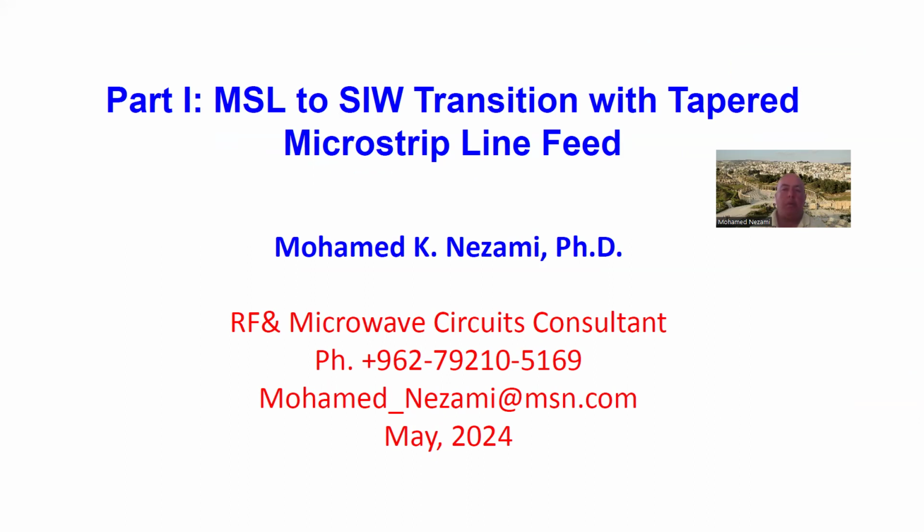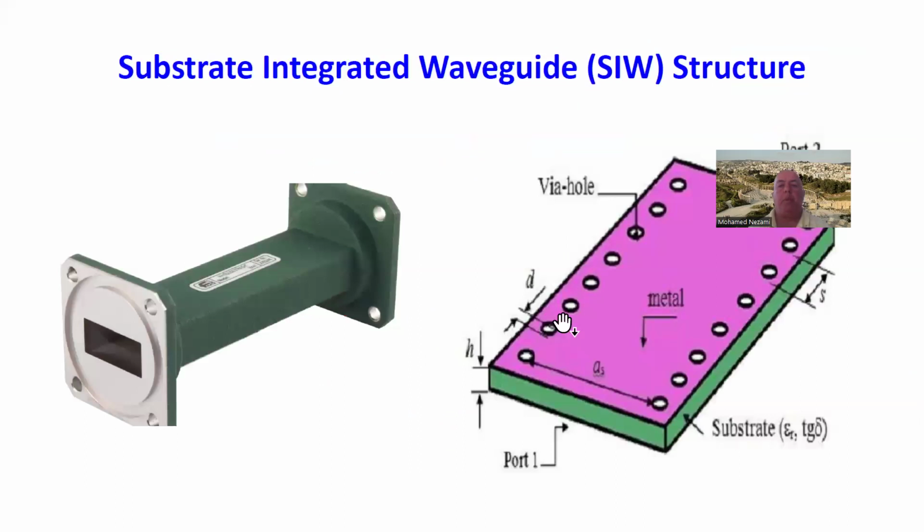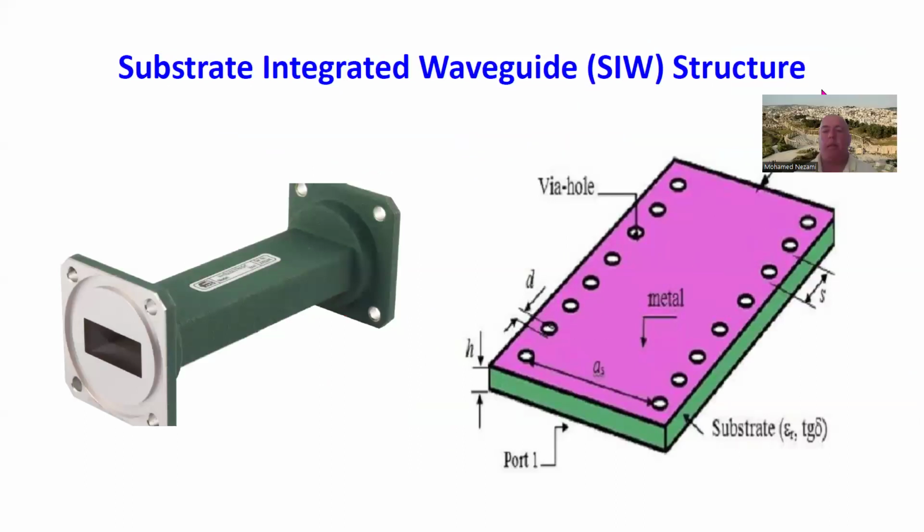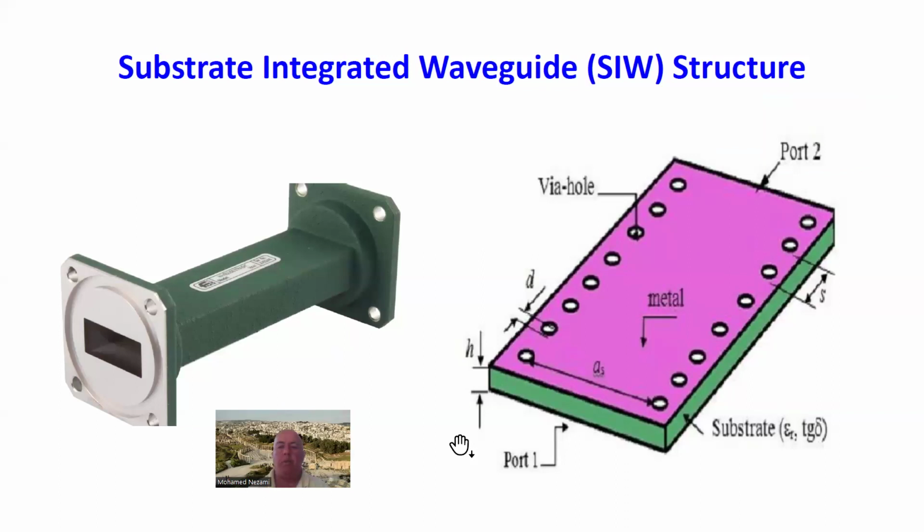As you know, the substrate integrated waveguide, unlike waveguides, has an input and an output. Now, one of the things that we have to do is somehow attach a connector or reach out to a MMIC chip on the board. So whenever we implement anything in substrate integrated waveguide, we have to get back to a substrate to microstrip line implementation. And that right there is a transition.